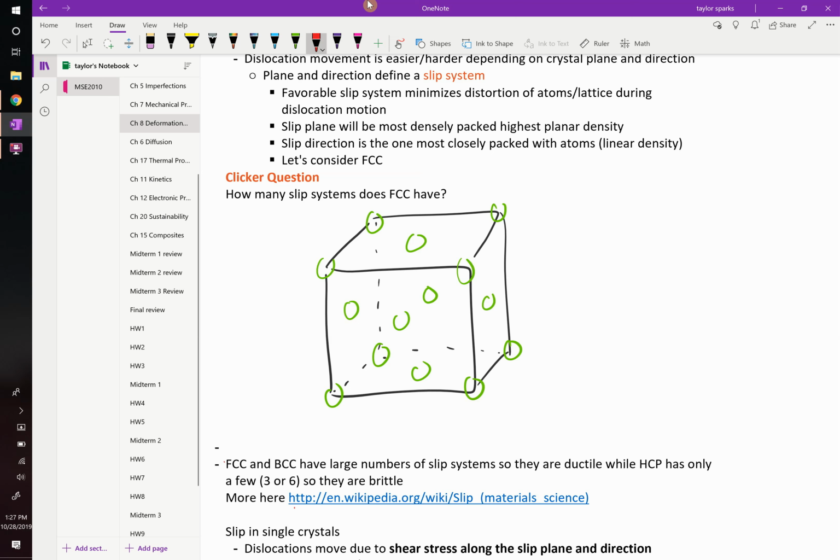We'd pick an origin. Let's go through the exercise again. If I wanted you to draw the 1-1-1 plane, let's pick this as our origin. That's typically the one we want to do. How do we draw it? First we take the reciprocal, and it's still 1-1-1. That means that it intersects the x, the y, and the z axes at 1. So it's going to intersect right here, here, and here.